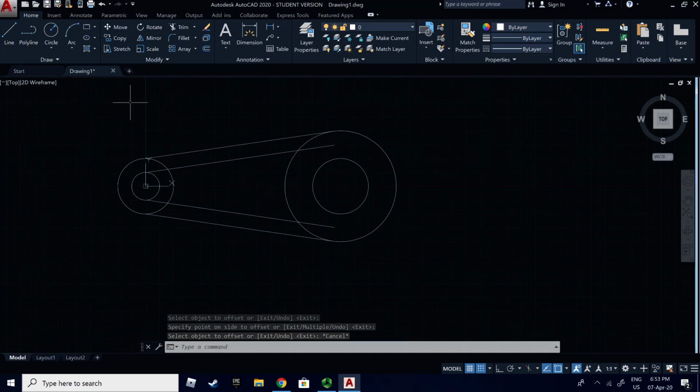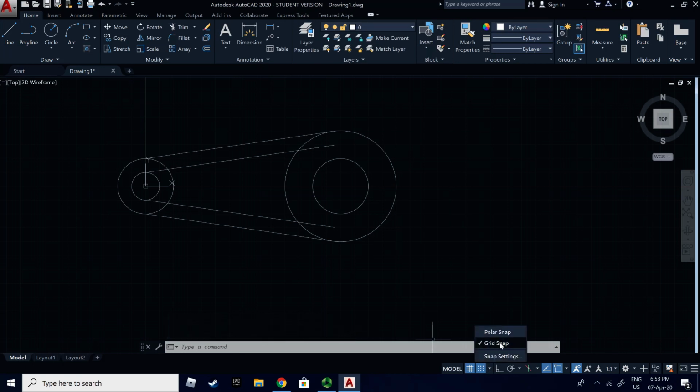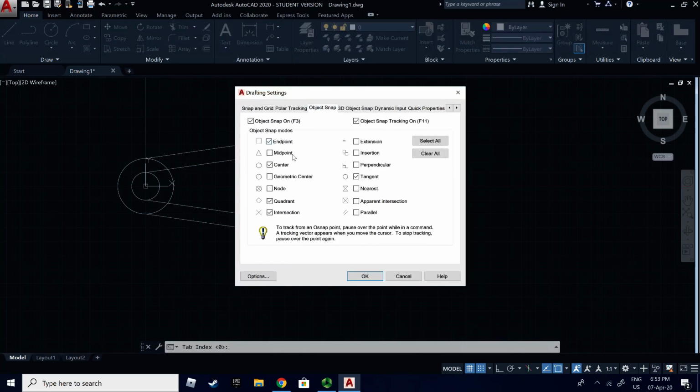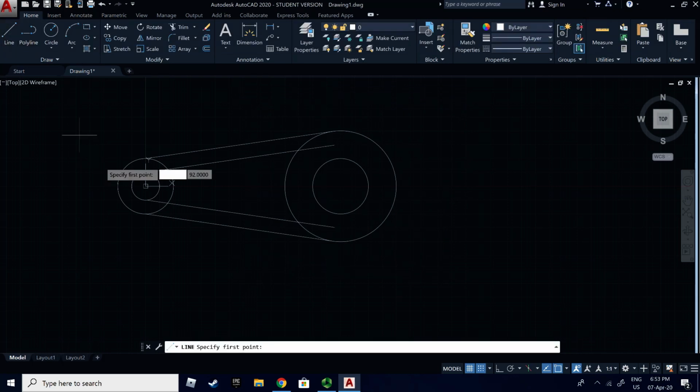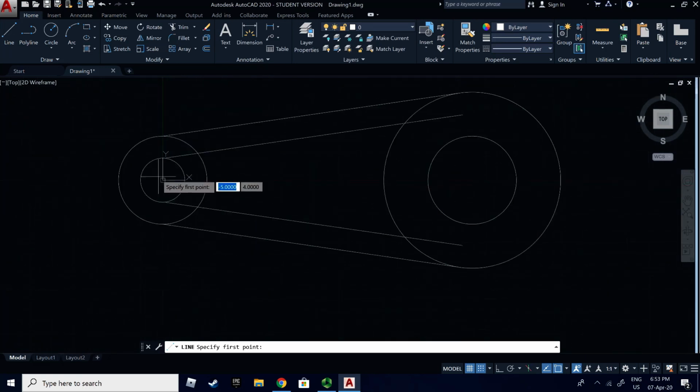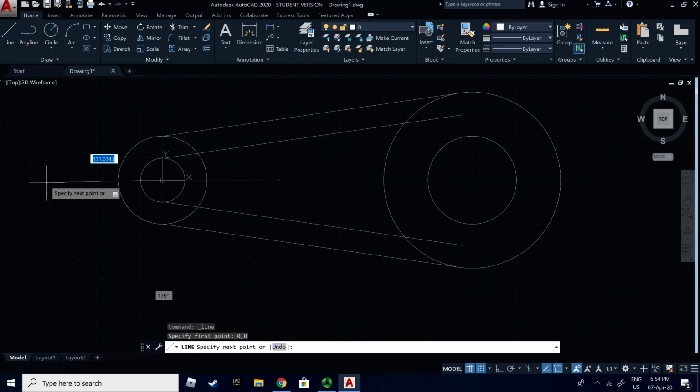Okay, next I'm going to work from the center of the circle. I need to make a few lines. Basically, later on it will become the center line of the circle, so I need to check the setting whether I need to open it. Okay, this is already the center of the circle. I'll just make some lines here. I'll specify the first point 0, 0.